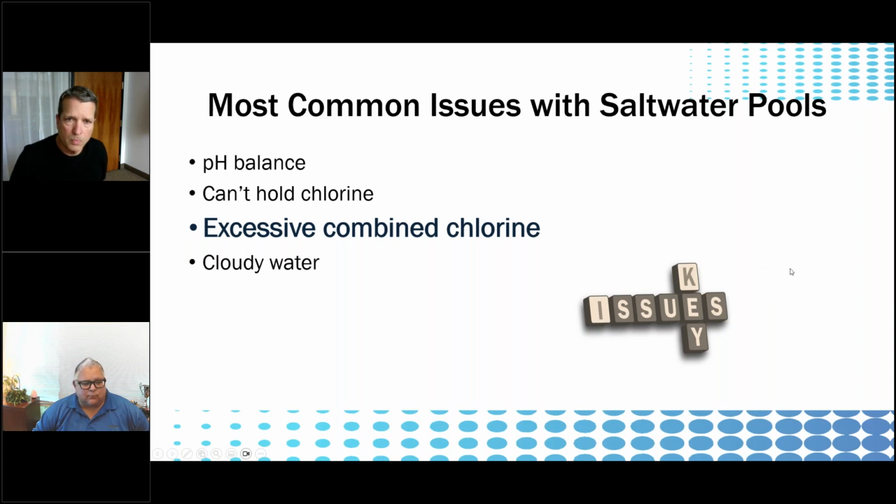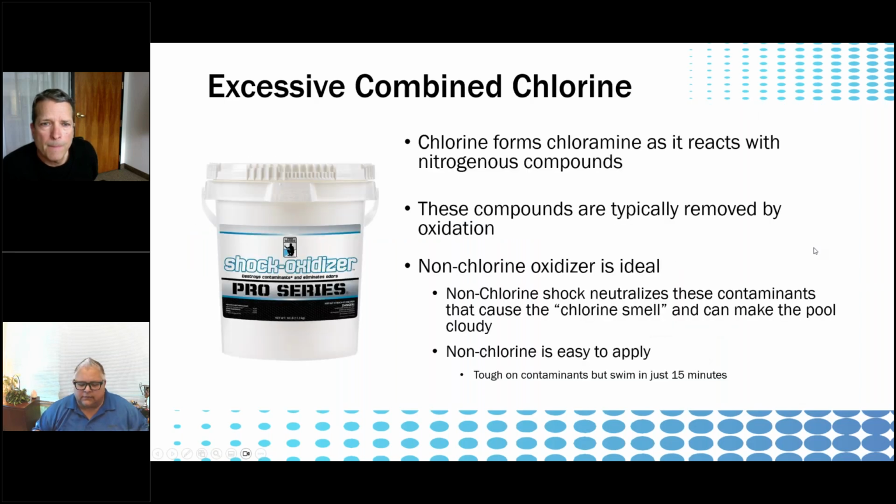Excessive combined chlorine, and we're rolling here to the end. I'm wrapping up so we can take some questions here. Excessive combined chlorine can be an issue in saltwater pools simply because we don't shock them. And a lot of times we don't even hit the boost button. We just let it roll along because you're constantly making chlorine, and that's great.